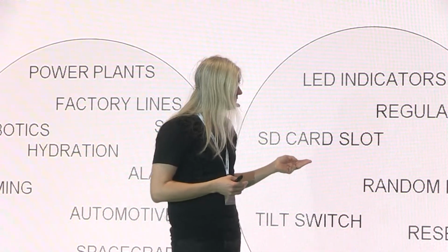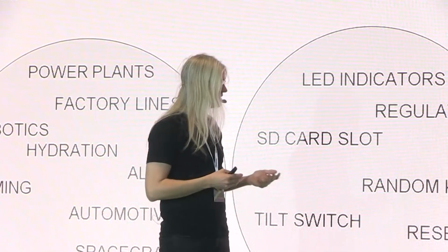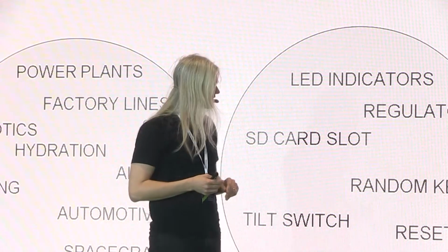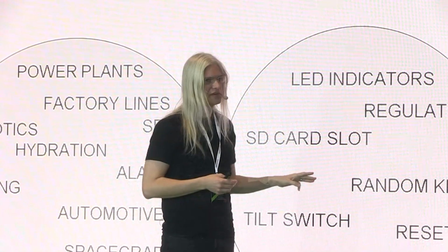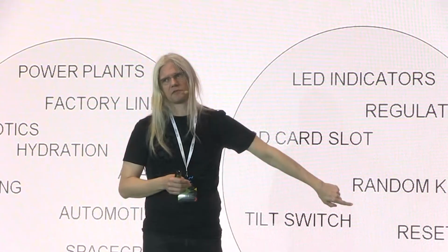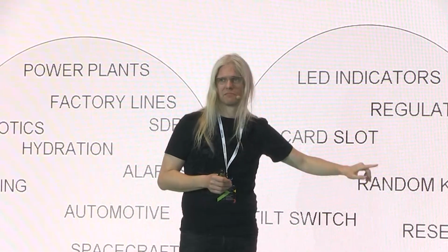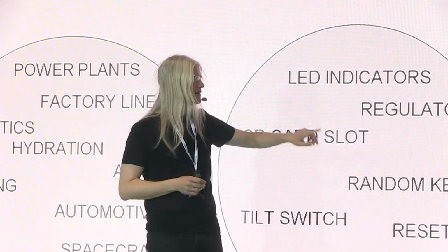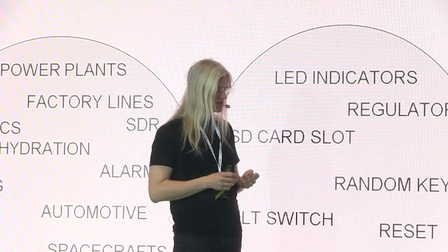So SPI, I2C, MDIO that they use in network. You can do pulse width modulations, but be a bit careful with that because you probably need real-time patches for that to get right. You can read flash chips and so on.